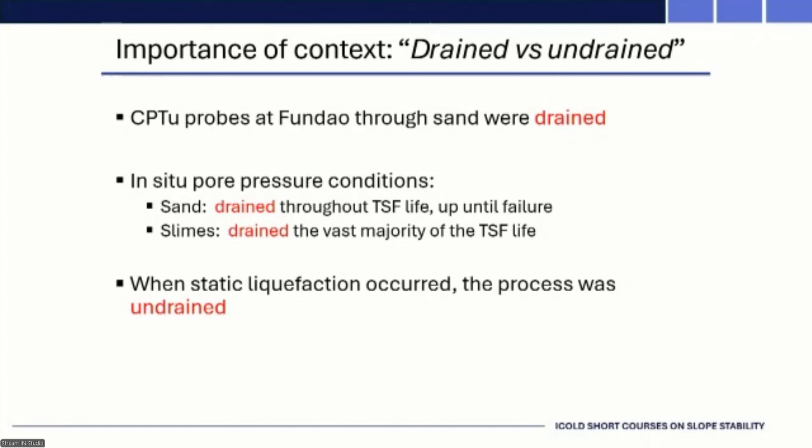The slimes or the fines below that sand were drained for the majority of the TSF life. It was built up slowly, pore pressures were probably dissipating, but when the critical condition was triggered, it transitioned to undrained. And that's when static liquefaction occurred at Fundão. And that was the finding of the Morgenstern forensic report.